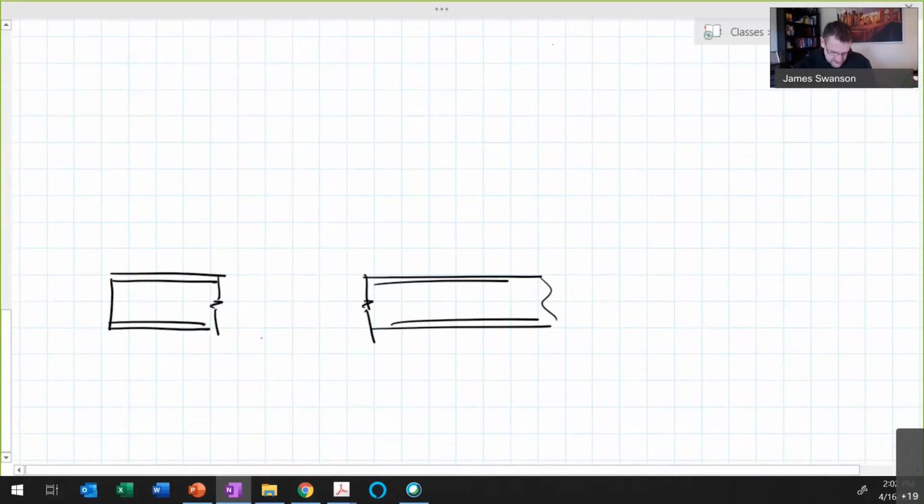So the shear force would be this. That would be the shear force on the left-hand section. That would be the shear force on the right-hand section. So that is a shear force V. And if you're looking at the diagram at the top of this page, you can't see that shear force. The external loads affect the shear force, but the shear force itself is an internal thing.